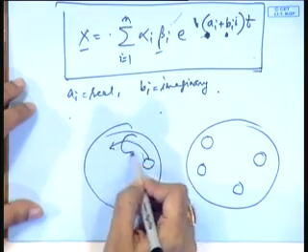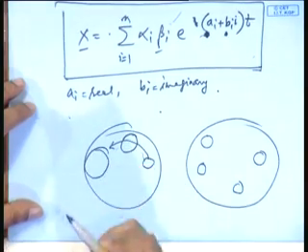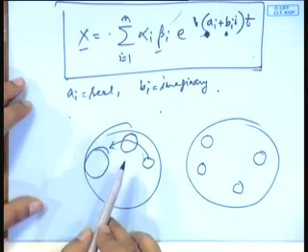That is how accidents in industrial plants that you hear of actually happen. Hotspot means a small region in the reactor where the temperature grows suddenly, and then it starts to gather in space. For example, if you started over here and then it goes over here, it becomes like this, it goes over here, it becomes like this. This is how a hotspot is generated.